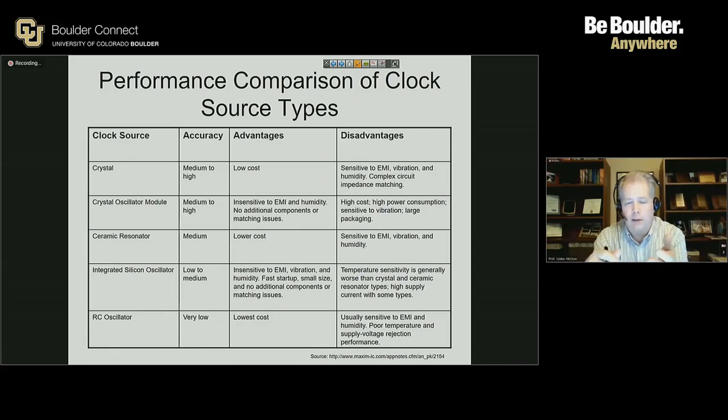The downside of it, besides cost, is that the signal strength of that TTL clock output is very strong, and it introduces a lot of noise in and outside of your system. So you can see effects across your electronics in terms of the noise introduced by that oscillator module, but it can radiate, and nearby or even a little bit further away electronics could be picking up the noise that's generated by that clock source.